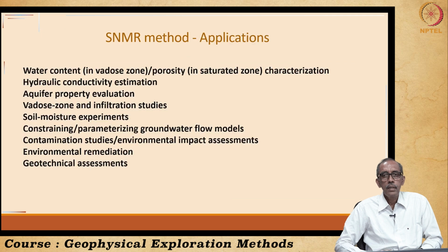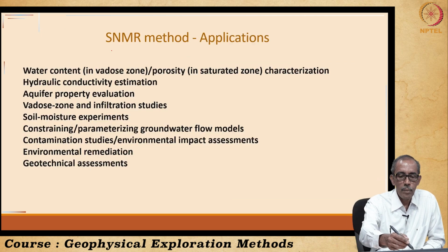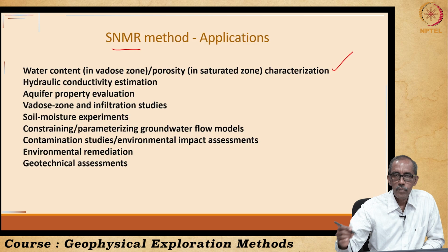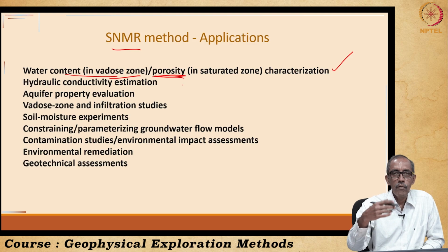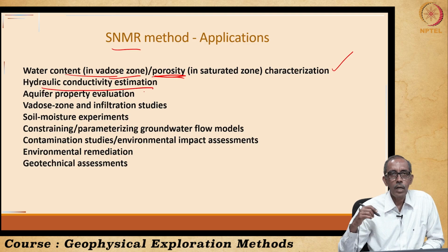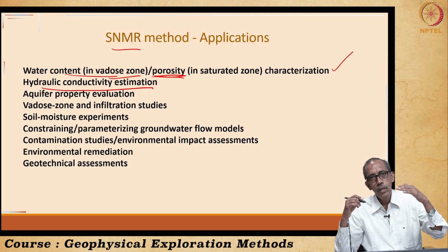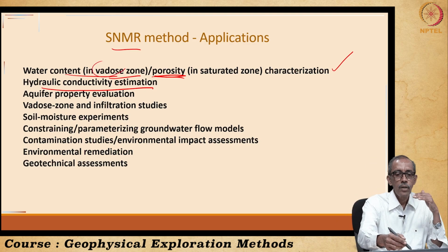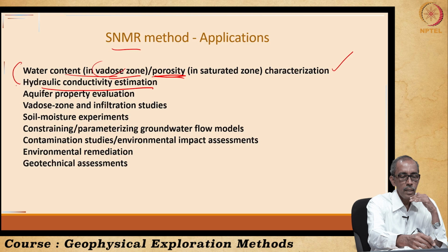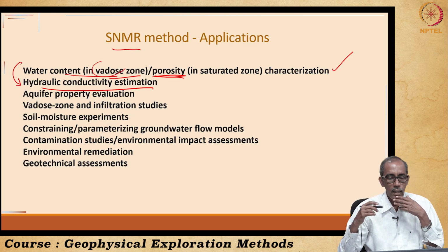To conclude, the broad applications of SNMR are, as we had seen repeatedly, first, to understand the water content both in the Vadose zone and in the saturated zone, where water content refers to porosity. Number 2, it helps us to also understand hydraulic conductivity. How? Using some empirical relationship. Please remember, NMR does not directly measure the hydraulic conductivity, it measures only the water content. Using that, with an empirical relation, we can determine the hydraulic conductivity.